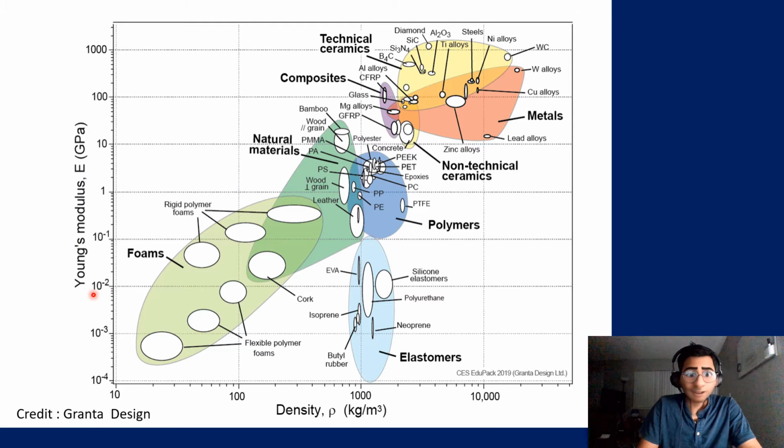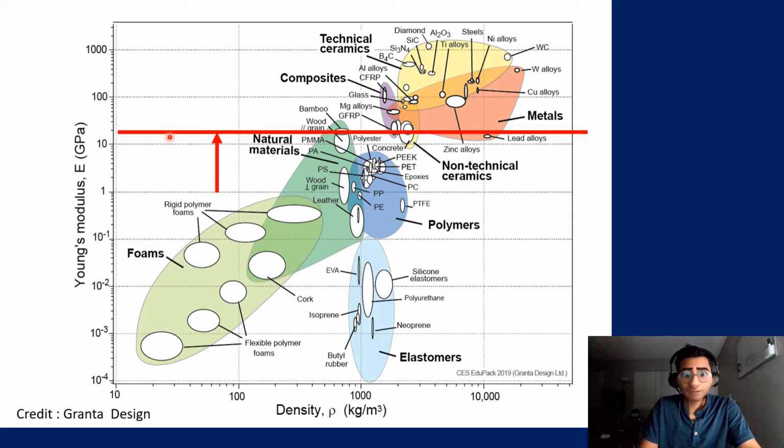This particular one has the y-axis listed as Young's modulus and density. You can plot various different axes. For example, if you are calculating factor of safety, you can look into stress, yielding strength and ultimate tensile strength, and plot against that. But for simplicity of this discussion, we will focus on how we select the material. Based on the previous equation, our objective right now is to increase modulus of elasticity. So just follow this line, move it up, and you can find which materials have high Young's modulus.